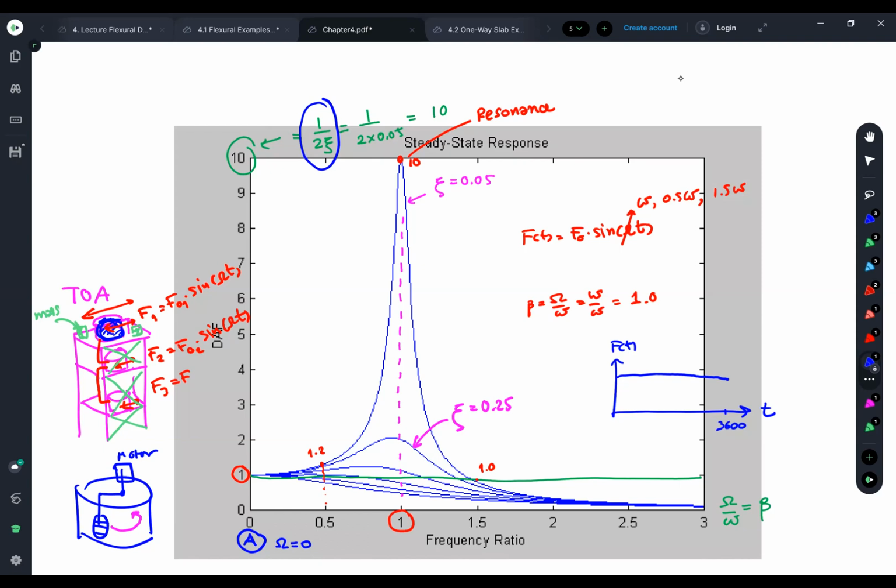Therefore, within 1 hour, remember our building is subject to the earthquake, the wind loading, or any other type of excitations. It's just 1 minute, 2 minutes, or maybe just 10 minutes or 1 hour at most for a typhoon or a storm, for example. An earthquake, you are thinking about just maybe 10 seconds or half a minute, 30 seconds, and then it's gone. So when I say that the force function is largely constant for 1 hour, this is already static relative to the frequency of the building, civil engineering buildings. It looks like the world of static already.